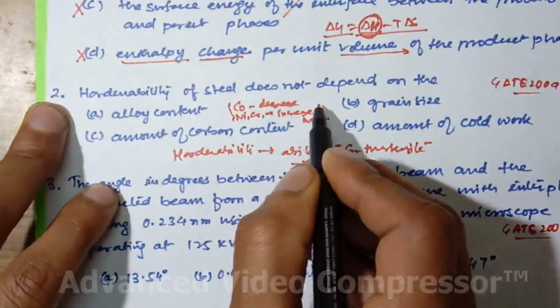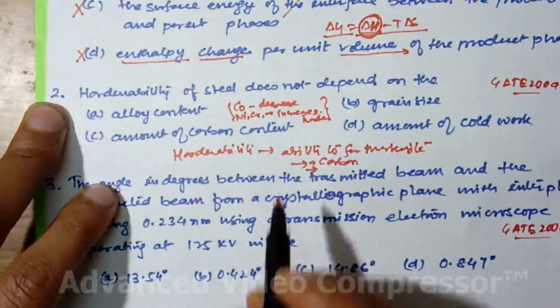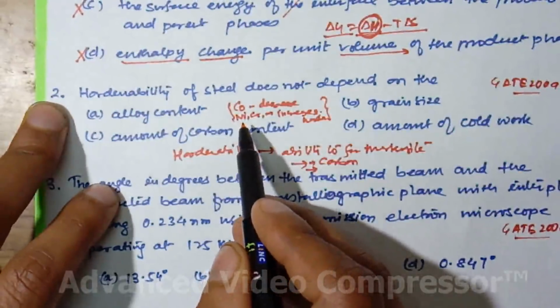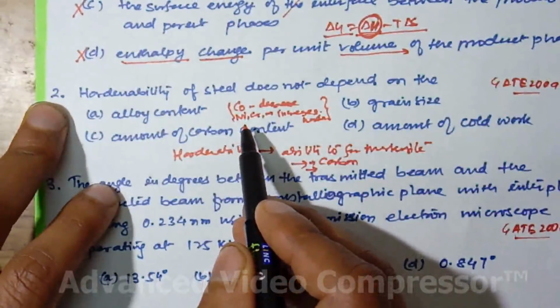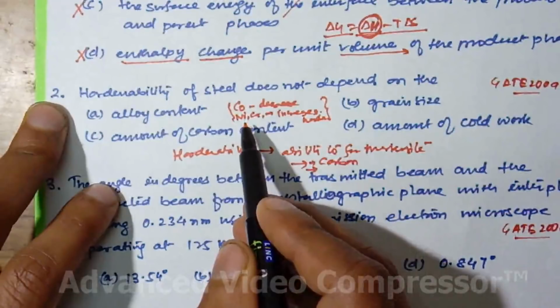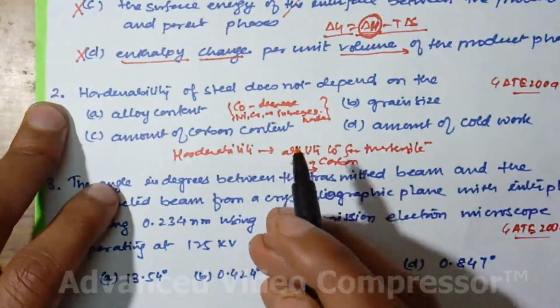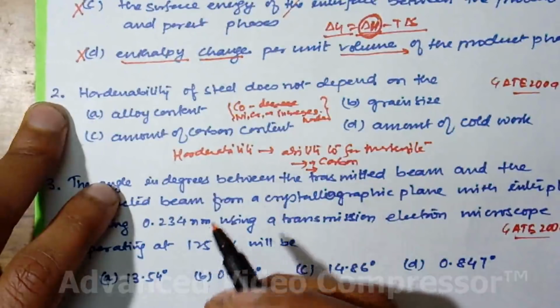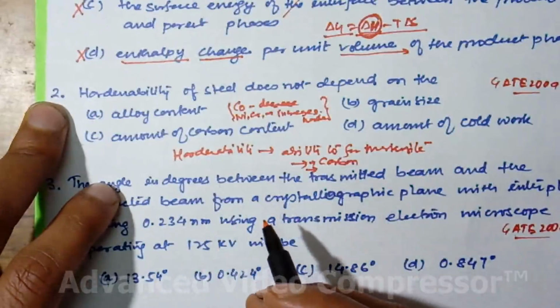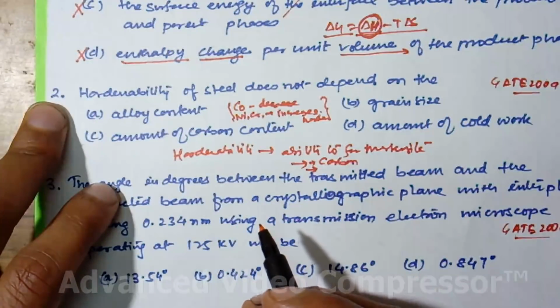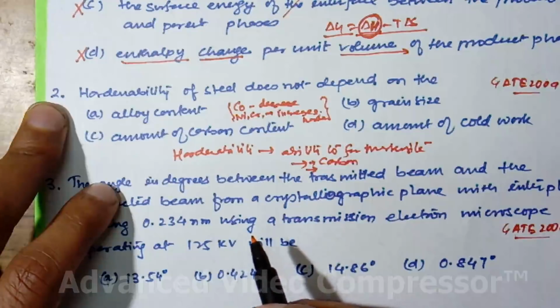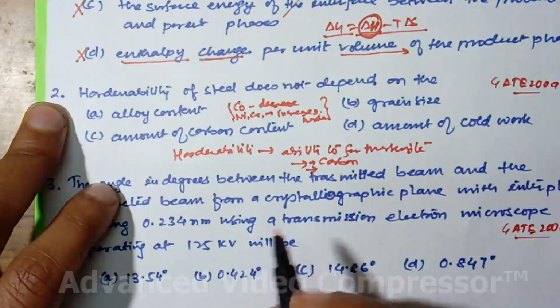And the reason for this is, when we dissolve cobalt in the metal, what happens? Cobalt does not dissolve completely, so it forms cobalt particles in the matrix, and these cobalt particles help in nucleation of pearlite during transformation.